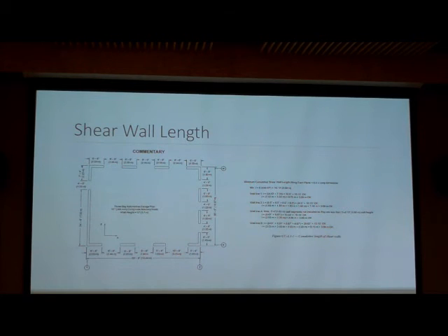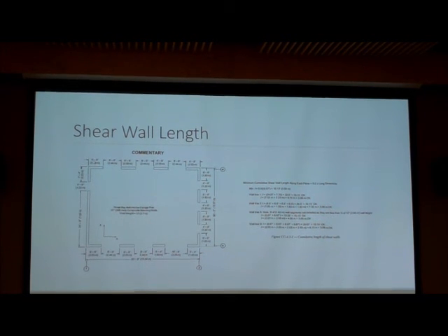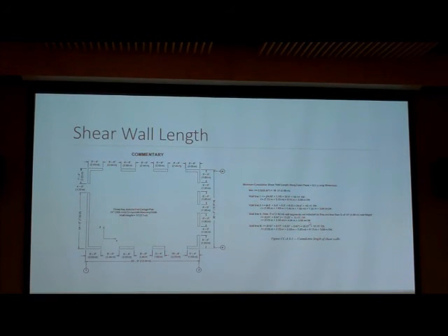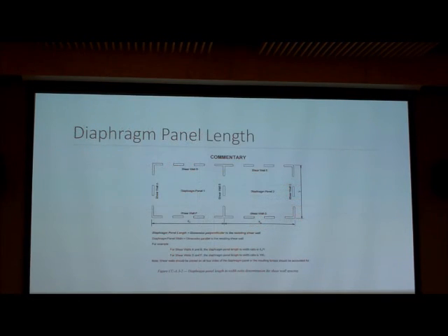And so if we look at this, we're going to add up our wall lengths that are the unobstructed through openings. So from here to here we have 24 feet 8 inches plus our 7 foot 4 inches. And that will give us 32 feet, which is greater than 10.13 feet. So we're okay there. And it goes through every wall line and checks to make sure that we're greater than 10.13 feet. And so it's pretty simple. It's not too line crunching because it is using ratios and simple equations, not big, long calculations.